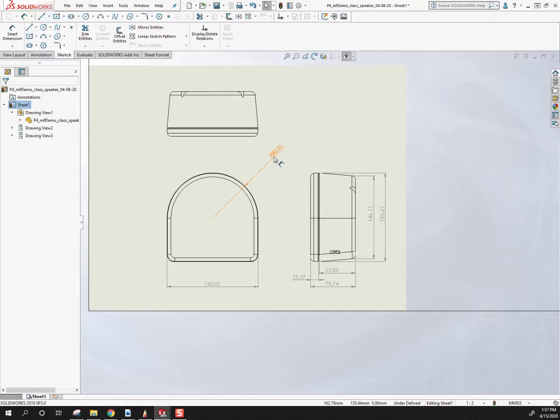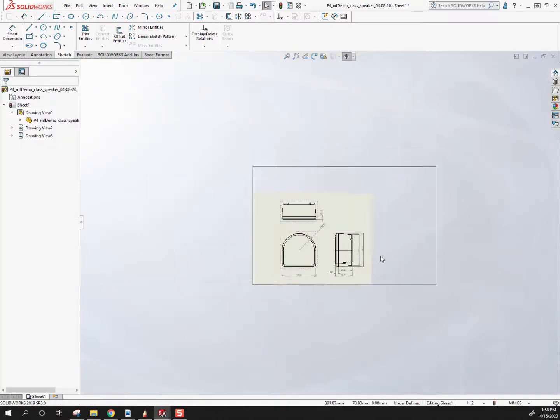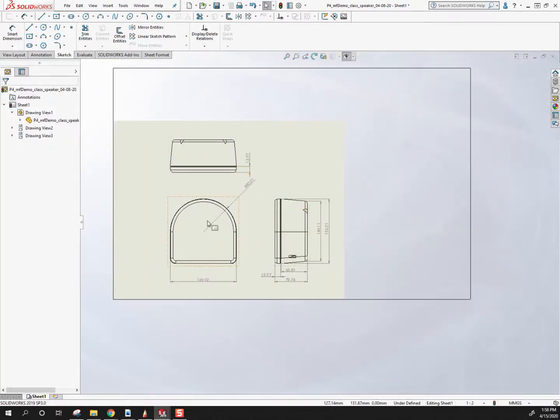Or if you're working with a client and you're doing drawings for them, you will probably follow that. You will follow their standard and what they're doing. The short answer to your question is yes, you could put this dimension up here. The long answer is that some of these standards and some best practice in dimensioning advise to keep the dimensioning grouped where possible.